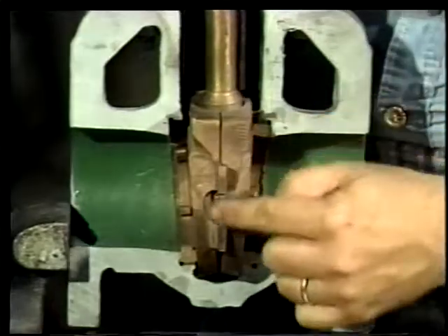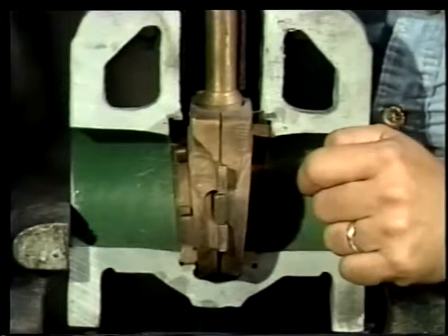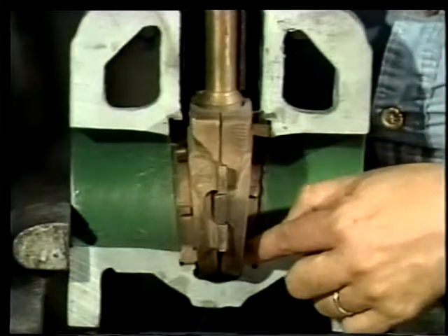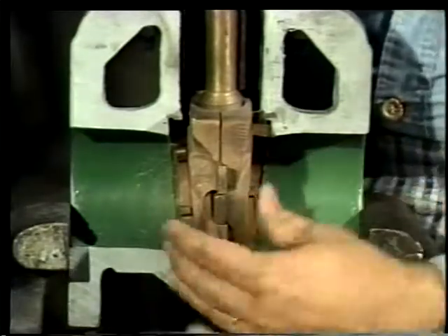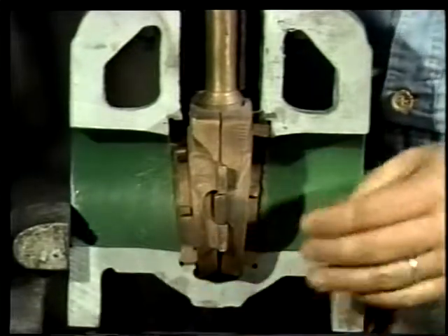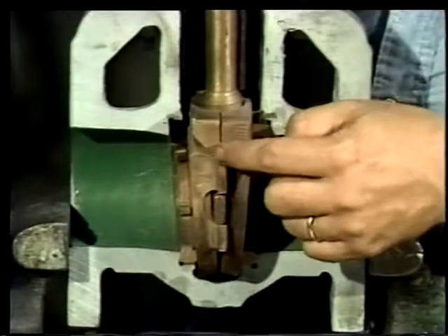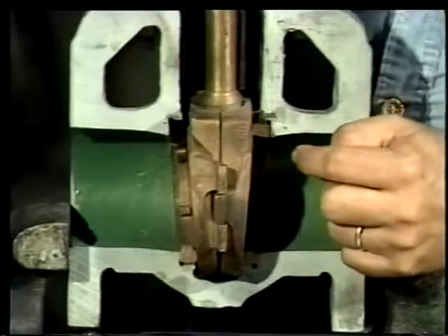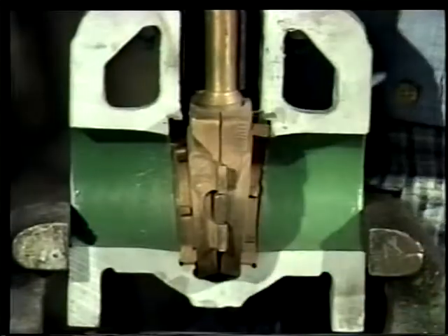It is directed by a set of guides that keep the disc in line as it closes. The disc does not touch the seating surface until the closing point is almost reached, and then the disc is wedged in between both seats. The wedge disc may be split down the center. In this way, each half will rest somewhat independently on the opposite valve seats.